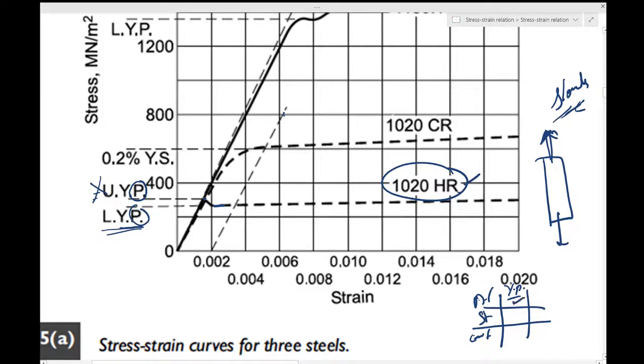Someone else somewhere has done these tests, and there are these design tables where these values are available. Those tabulated values which we use in designing are actually the upper yield values. It's not specified that it's the upper yield value in the table, but that is the case. So that is what they say by saying that unfortunately it is the upper yield point which is often tabulated without being labeled as such in the tables of properties.